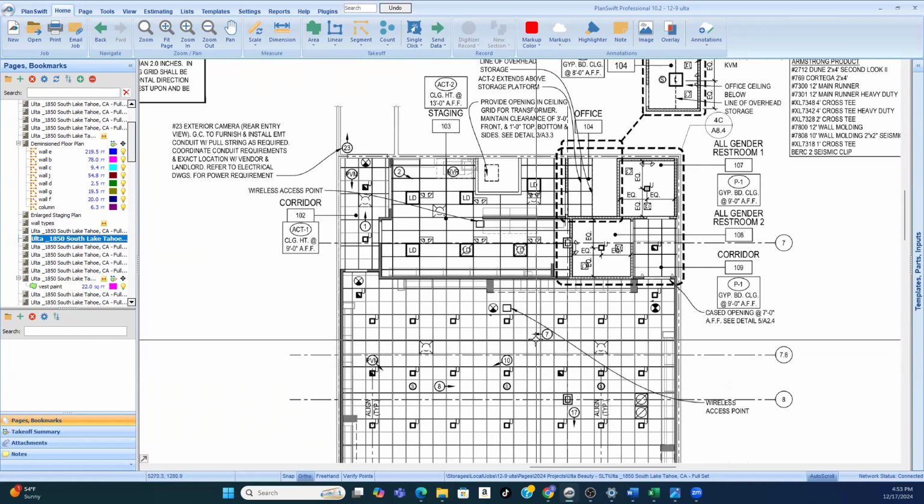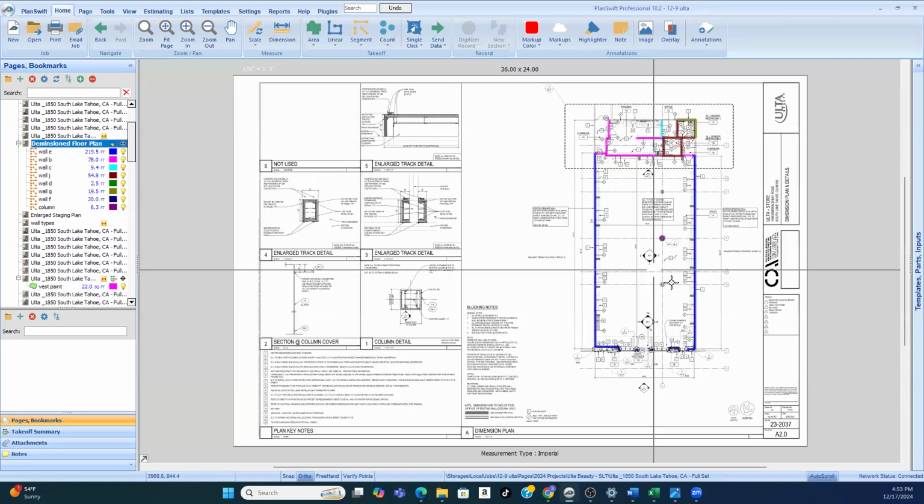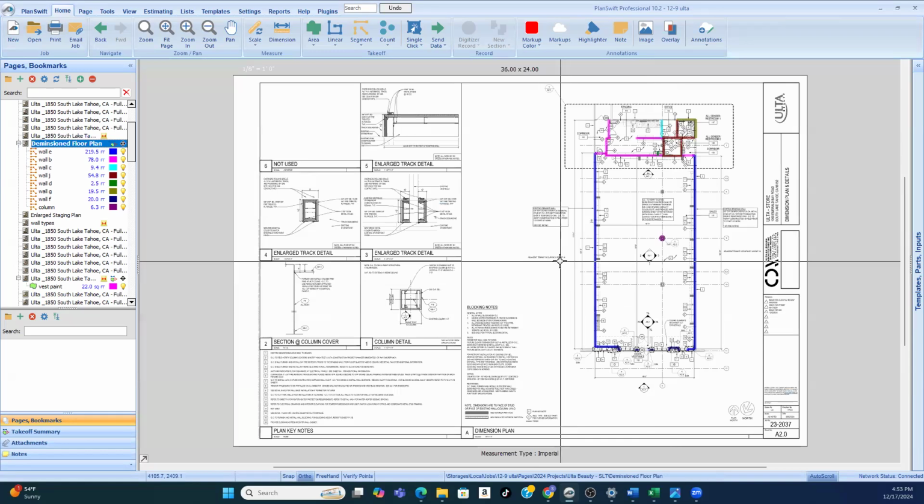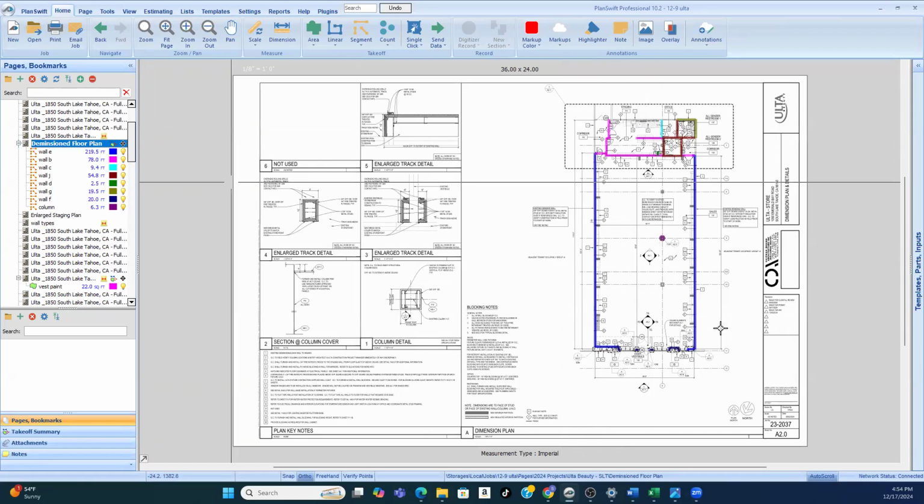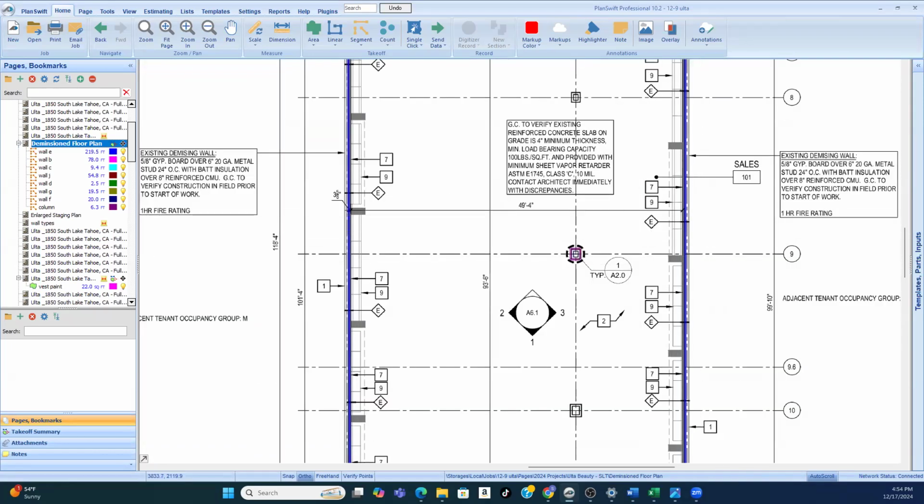And third thing is most commercial ceilings are at least 10 feet, okay, except for exterior. The exterior is going to go the height of the ceiling, but interior, I don't think you could ever go wrong if you can't figure it out one way or another by saying the interior walls are probably 10 feet. I'm going to go 10 or 12 feet, okay, and you'll probably be okay. But when we have our next class, I'm going to have a different set of plans so I can show you specifically how a section view is supposed to look and work, and it does look and work the way it's supposed to. Sweet.